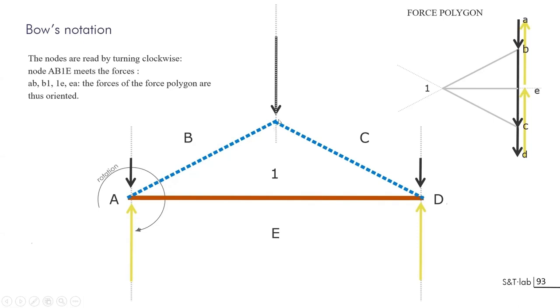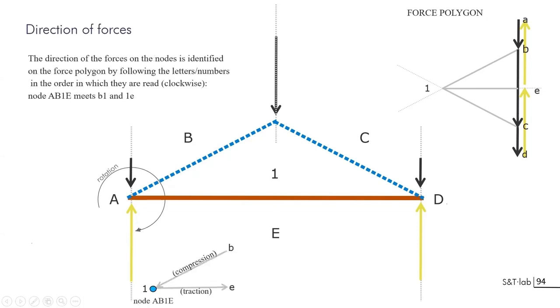Second principle, you have to know what will be pushing on the bar, and this bar will be in compression. You can do the same exercise for each of the bars, and you won't be making mistakes about this in getting the result. Of course, you know that the force polygon is the representation of force, so you can measure each of these bars, and you can have a look directly at the proportional length of each of these bars to see where the main forces are.